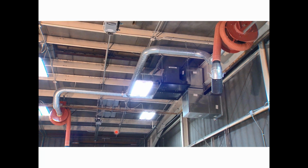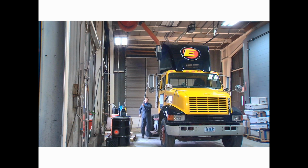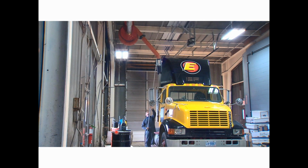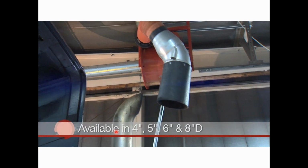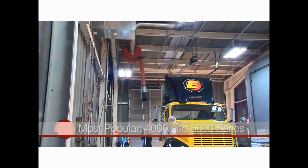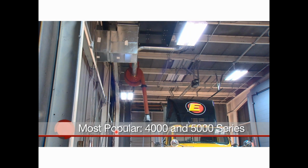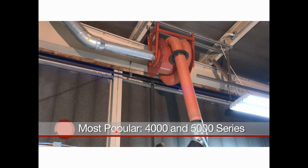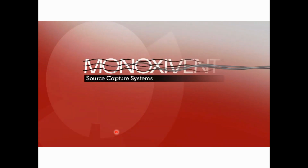Now, basically, you can see that they're all tied into a central exhaust or a central fan. And now when he wants to take it off, again, very simple. Puts the lifting pole into the lifting sleeve, lets it go. He'll pull it down, and then the spring will pull it back up and out of the way. One of the things I like about this particular video is notice how relatively short the length of hose is. You don't need a lot because you're not really going a great distance, and that's a cost-saving measure.